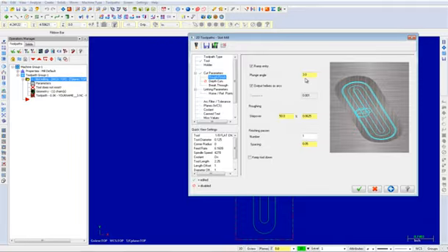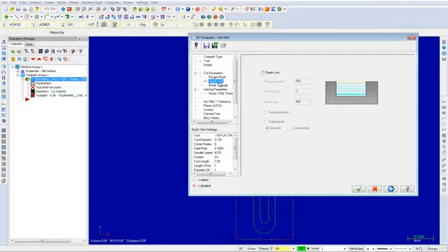Once the parameters have been set, choose Depth Cuts. Enable this option and input a max rough step of 0.1. Ensure that the number of finish cuts is 0 with a finish step of 0.05. Finally, ensure that Keep Tool Down is enabled.